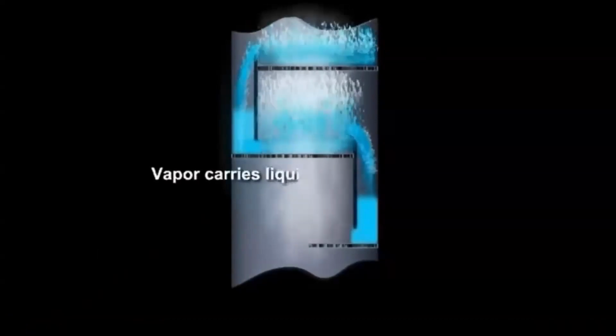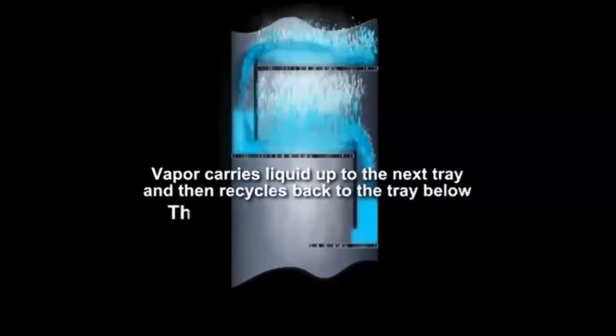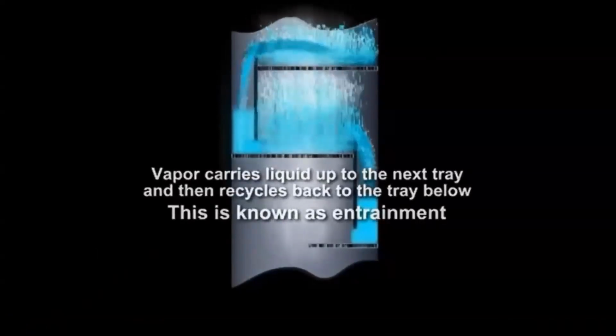And then the last term is flooding, or also known as entrainment. Condition occurs when the froth level approaches the tray above. Flooding occurs at high vapor rates and results in a significantly lower efficiency. At these high vapor rates, the vapor carries much of the liquid up with it to the next tray. This recycling of the liquid is called entrainment. Entrainment mixes the stages together and reduces the countercurrent effect of the column. Flooded columns are also difficult, if not impossible, to control, as the separation performance will decrease dramatically.